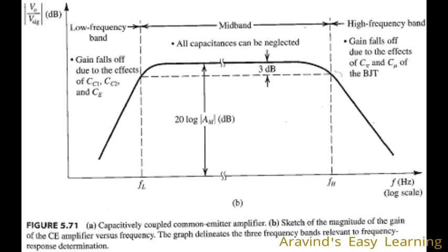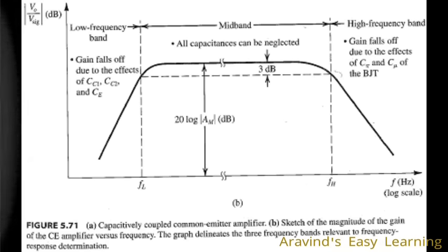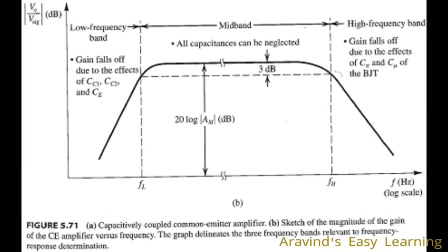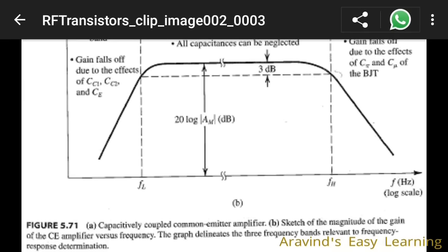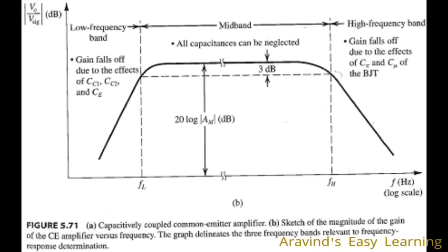What is bandwidth? You see, the bandwidth of any circuit basically is a plot of frequencies with gain. On the y-axis there is gain in decibels, and on the x-axis there is frequency in hertz. So we just analyze how the gain varies with frequency. Simple, right? We just look at how the gain is going to vary with the frequency, and we make a plot. And for an RC coupled amplifier, when we make such a plot, we get a waveform as shown here,